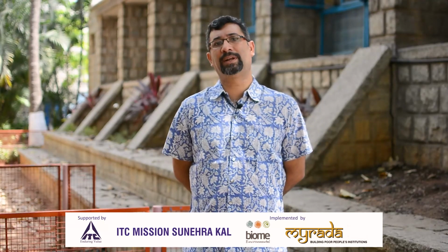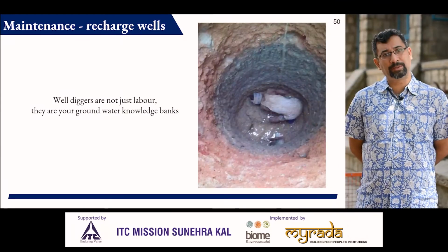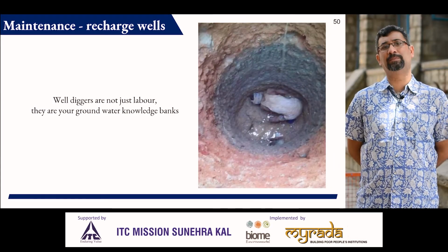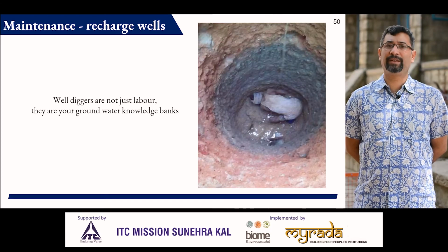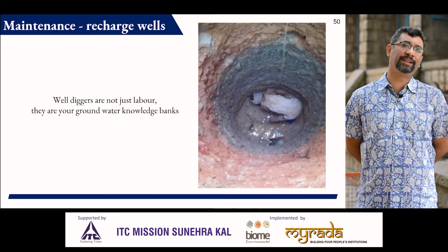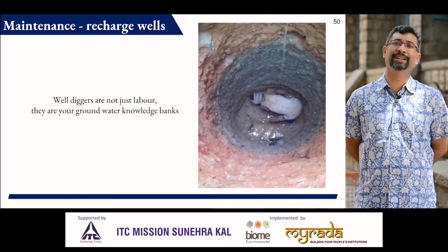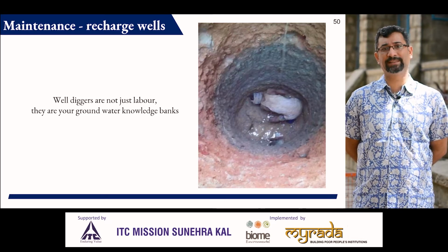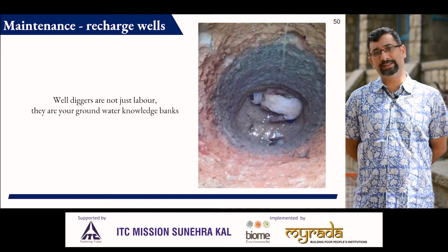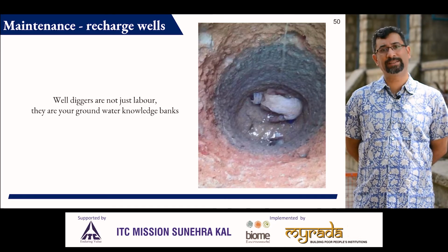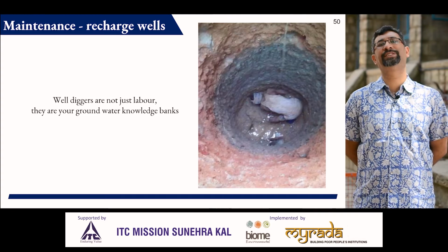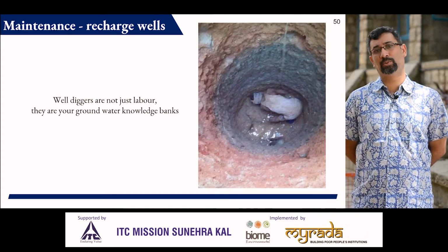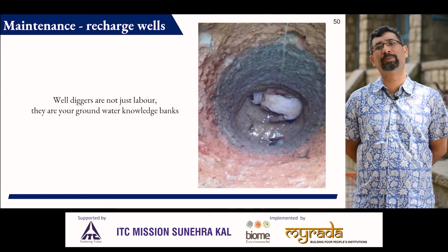Equally important in good management of your water systems is regular maintenance. For example, for your recharge wells, look at them once in 3 years to see if they need desilting, or if some rings need to be replaced. Here again, well diggers are going to be our partners, and remember that they are sources of knowledge. They can make observations to bring you insight into what's happening, and they are not just people who dig your wells.